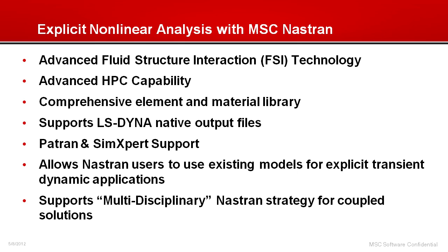It has advanced FSI technology, and it supports high-performance computing environments by offering distributed memory parallel capability. It has probably more than 120 to 130 different material models to support alloys, metals, all the way to ceramics, composites, gases, fluids, explosives, what have you.